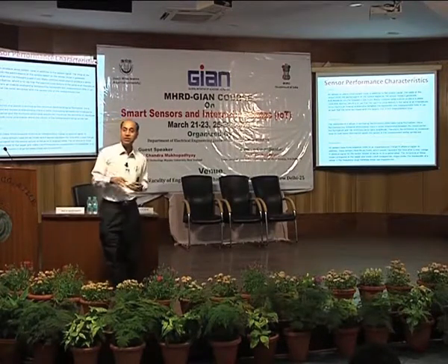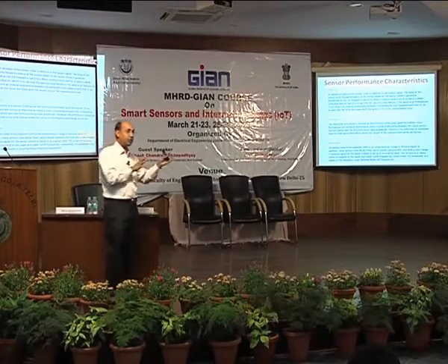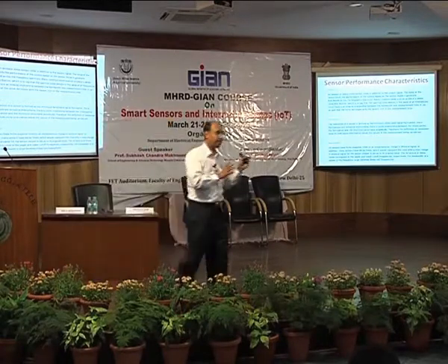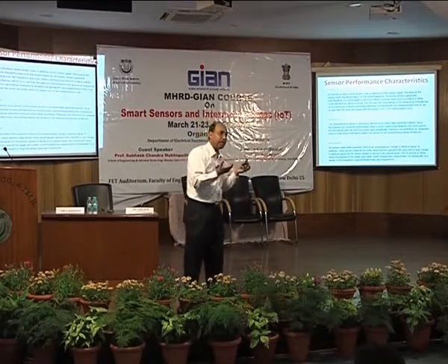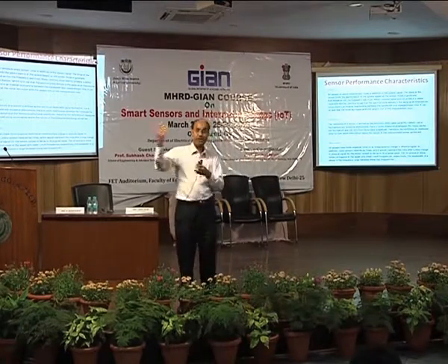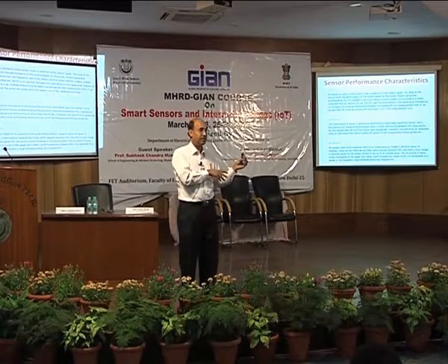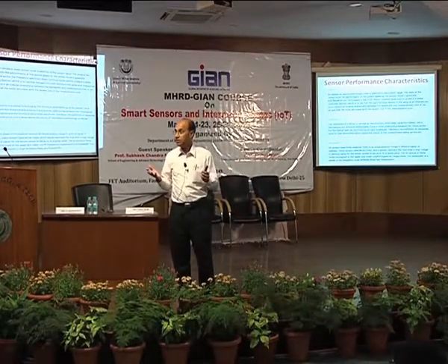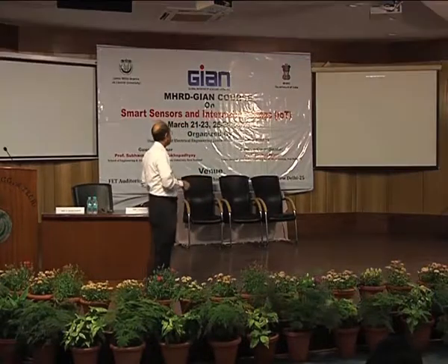Those are the things you need to be careful of, because you may have your sensor working perfectly, but your instrumentation circuit, because of lack of knowledge or understanding or lack of application, gives a completely different result, and you may blame the sensor, but actually the sensor is very good. So just be careful of those terms.